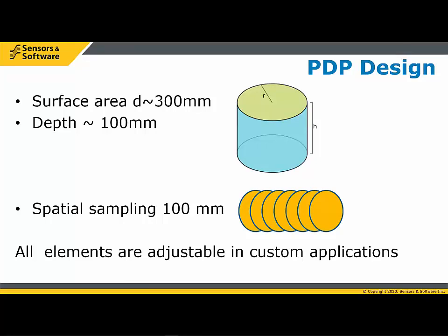The critical thing is, if you look at the footprint of the instrument, you want to have your lines set so that the footprints overlap. If you start running lines so that each line is further apart, so the areas of illumination don't overlap, then you have gaps in the data. So if you're doing adequate data sampling and you really want to build a proper map, you have to adequately sample the data. And that means having the footprints overlapping between adjacent runs.